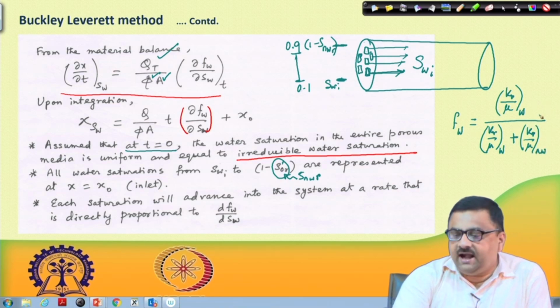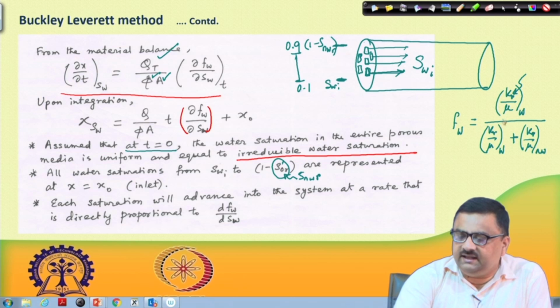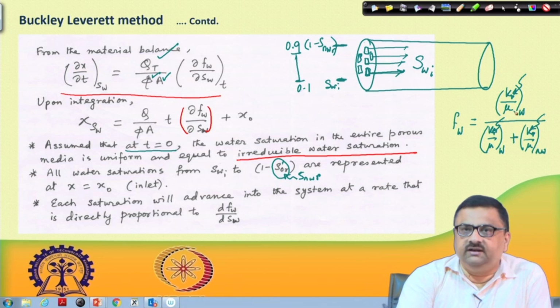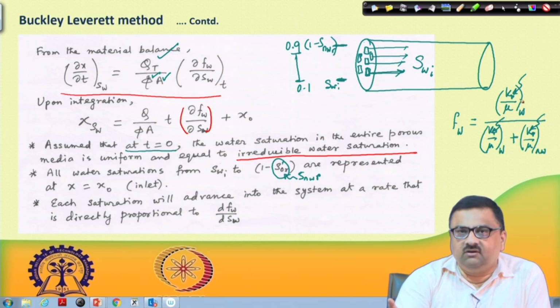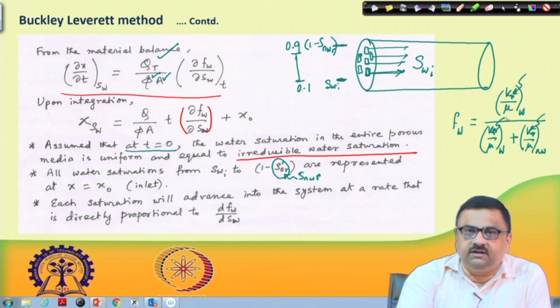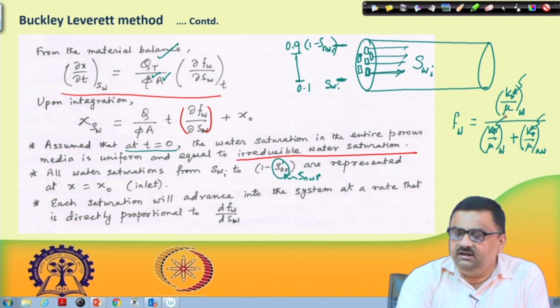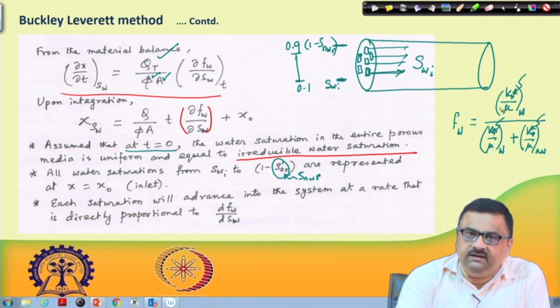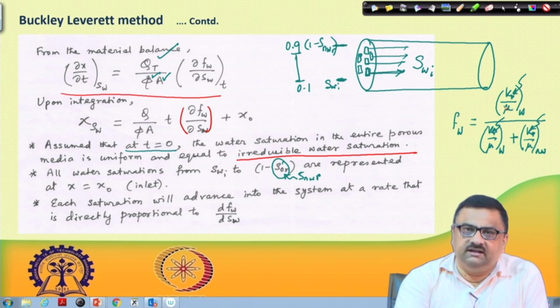So, and we know further in this case, this is Kr wetting, and this is Kr non-wetting. Mu is constant. Mu of the wetting phase, if it is water, is close to 1 centipoise, and one can figure that out. Similarly, if it is oil, oil has a viscosity which is known. So this mu can be directly plugged in, but Kr, we already saw Corey's relation,